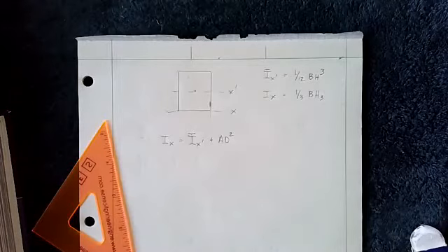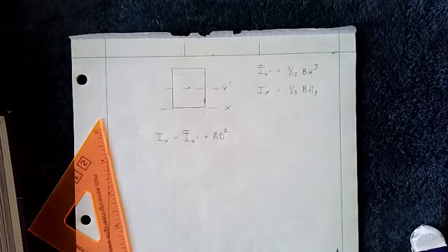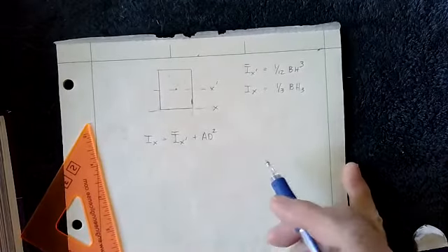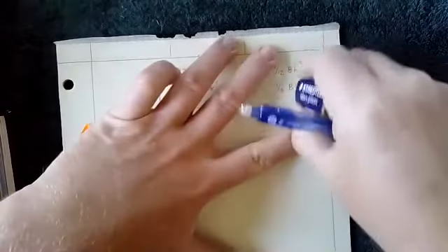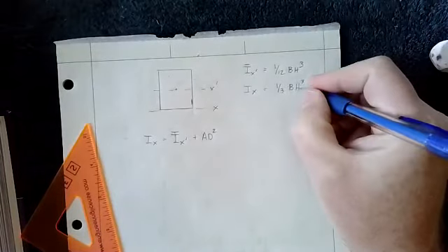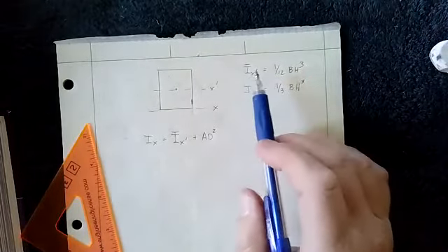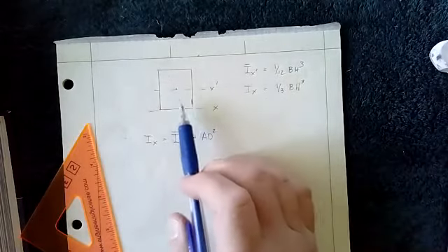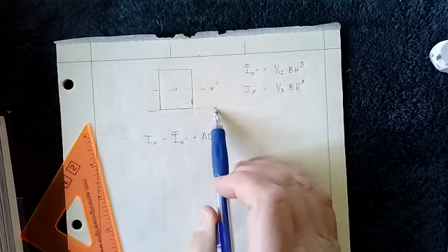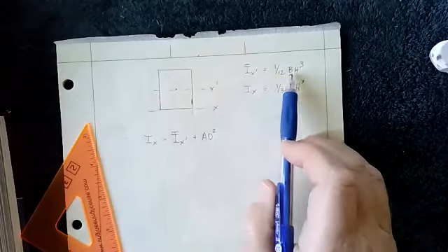Now I want to continue this discussion. The last couple of minutes I don't think could have been as clear as possible, so I wanted to reiterate this, and I should have written this as cubed, sorry. So it's not an H3 compound. Here's my rectangle. As I mentioned, if you're taking moment of inertia about the base, it's 1/3 bh cubed. If you're doing it about the center, it's 1/12 bh cubed.